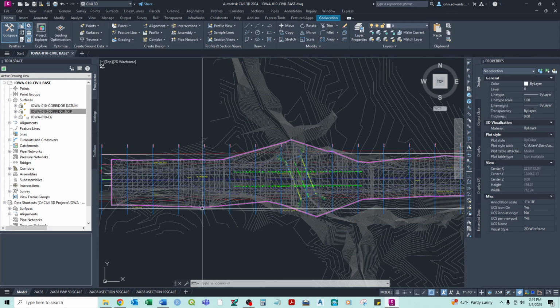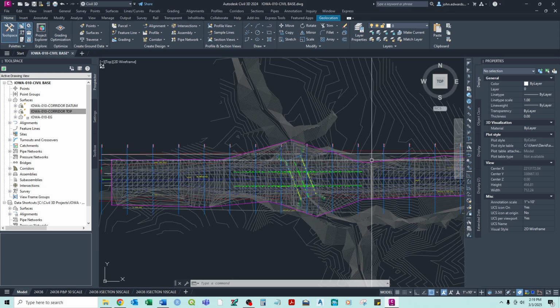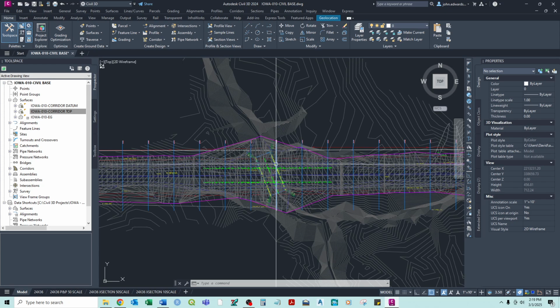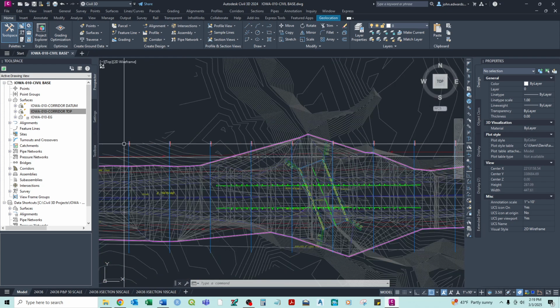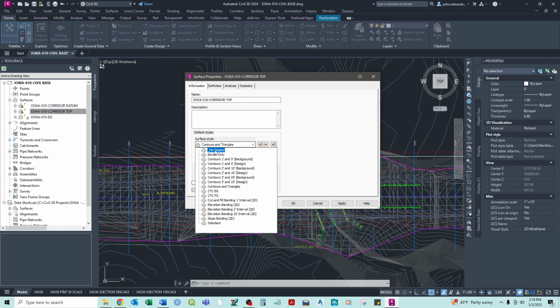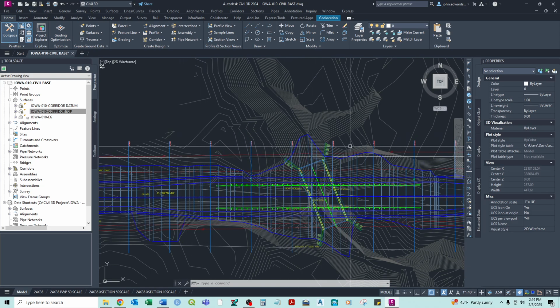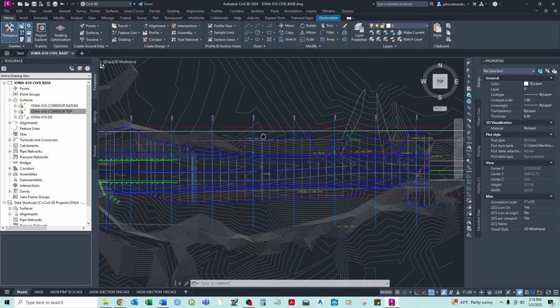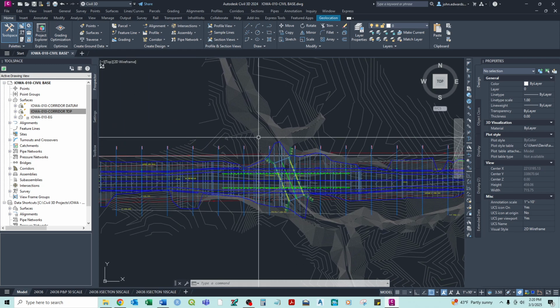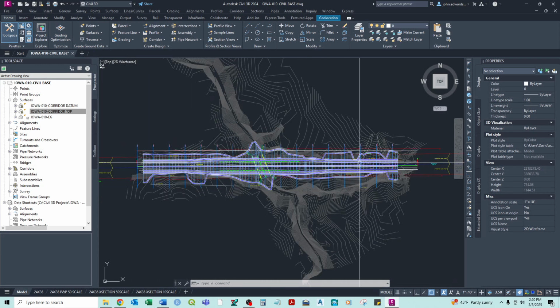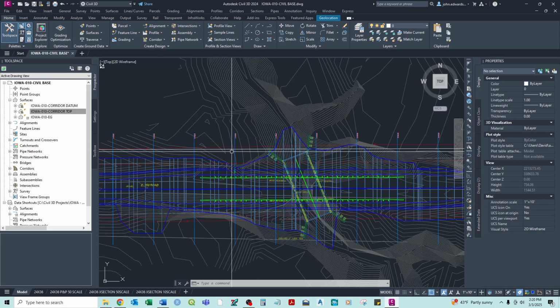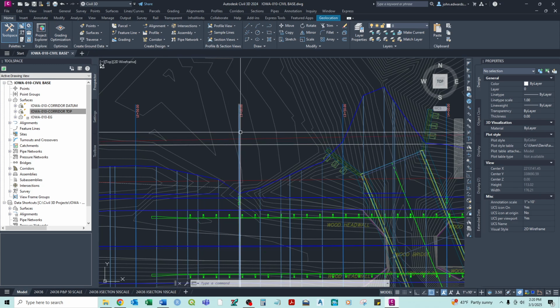And you'll note here it's a much smoother line and boundary compared to what our corridor was. If you remember that shape, and if I turn it off, you can see what it's doing is smoothing out around the edges, the far extents of our corridor, and not actually shrinking to the physical boundary of the corridor. That's one of the reasons our cross sections are off, because it's trying to snap out here to the edge of the corridor surface instead of right here.